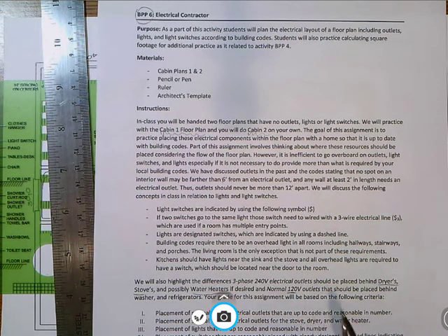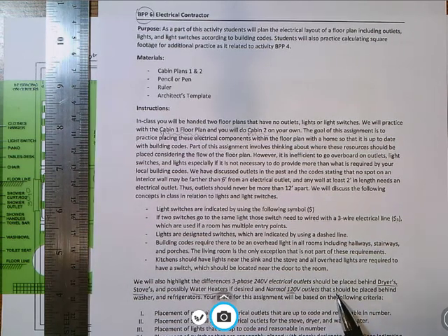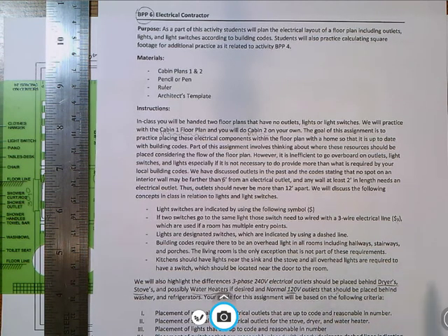That's where the terms 3-wire and 2-wire come into place. Now, all these still have a ground wire involved with them, and I'm not going to get into a huge amount of detail in this video about it, but when we get into drawing this out, I will show you how you indicate a 3-phase or 3-wire 240-volt outlet in comparison to a 2-wire 120-volt outlet.